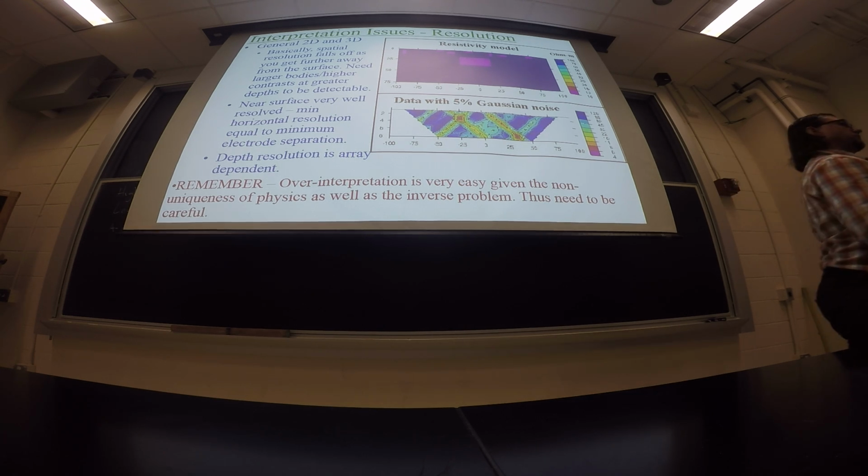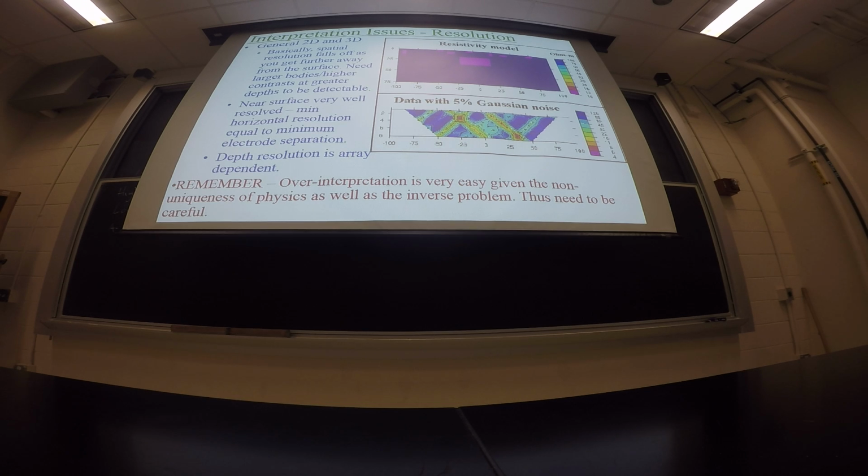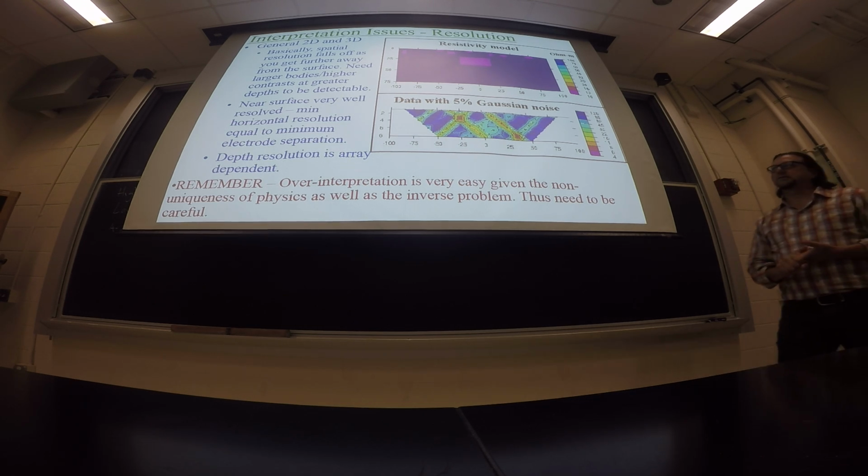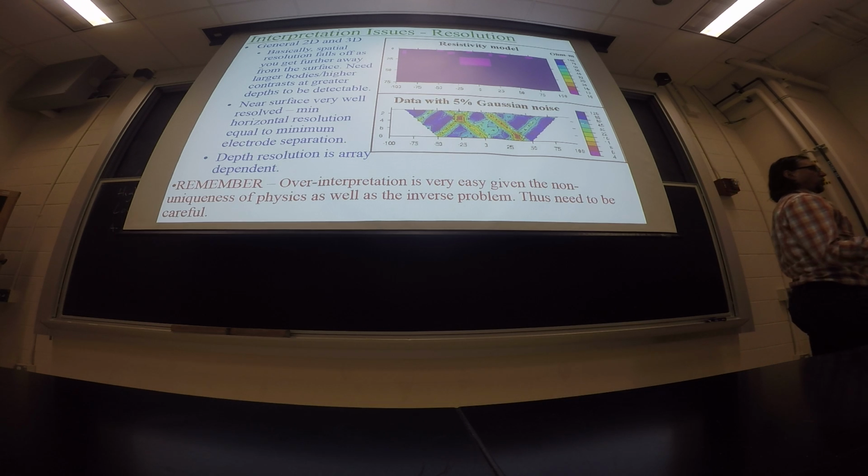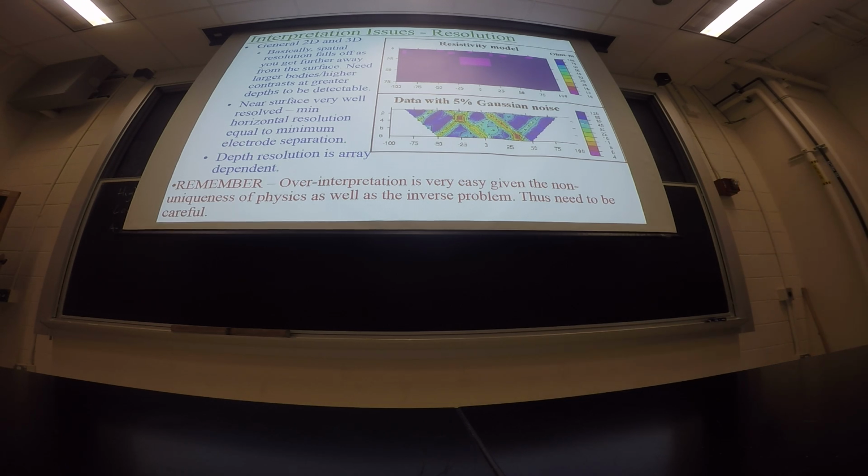Yeah. So this is used a lot for engineering surveys, for the near surface, upper 100 meters, for groundwater exploration. DC resistivity and a variant of it called induced polarization is used quite a lot in the mineral industry. They're for looking for disseminated sulfides and other types of base metal deposits. DC resistivity is not used much in the oil industry.